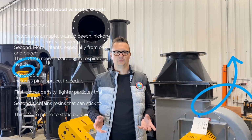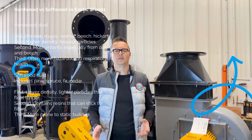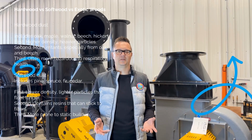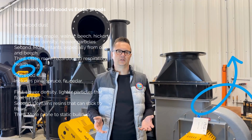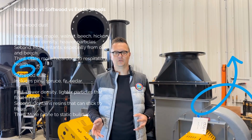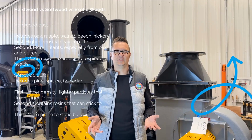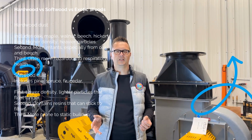Hardwood versus softwood versus exotic woods. Wood species dramatically affect dust behavior. Hardwood dust includes oak, maple, walnut, beech, hickory. First, higher density, heavier particles. Second, more irritants, especially from oak and beech. Third, often more hazardous to respiratory health. Softwood dust includes pine, spruce, fir, cedar. First, lower density, lighter particles that float longer. Second, contains resins that can stick to filters. Third, more prone to static buildup.